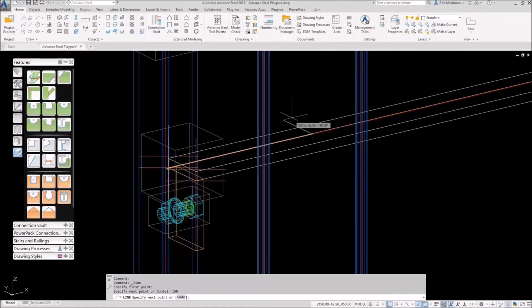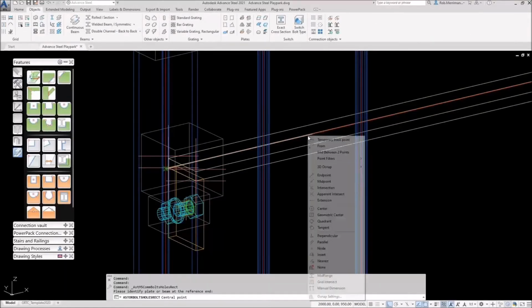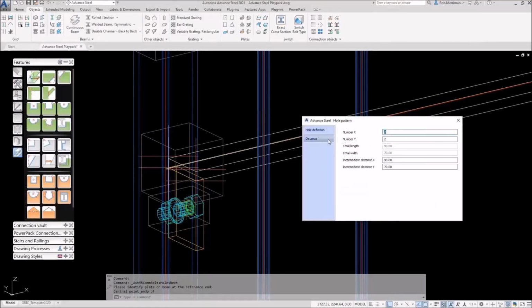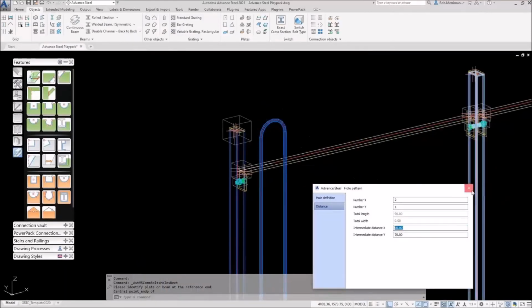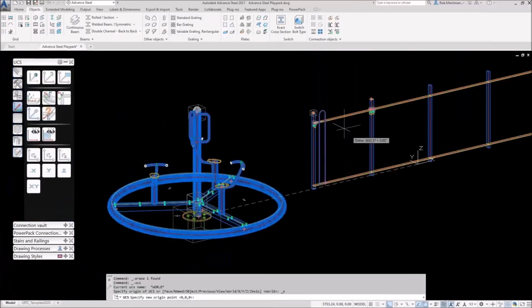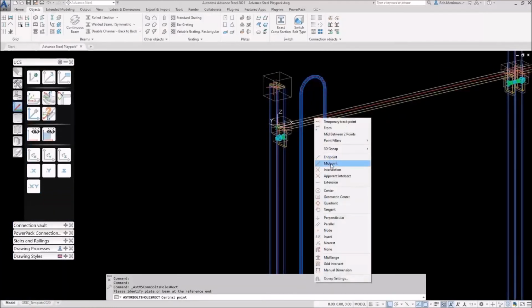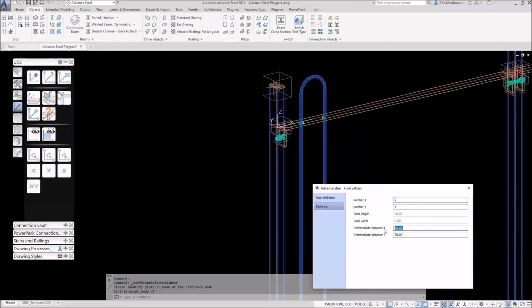So we're going to put our center point in at 150. I'm then going to say, right, put 2 holes in there based on the center point, which is that one. It will have put it in down there because I haven't moved my UCS, and everything in Advanced Steel is driven by the UCS. So we'll just put that back, choose the endpoint. They are going to be maybe diameter 11 or 10.5, just to allow that to pass through, and we want those at 100 centers.